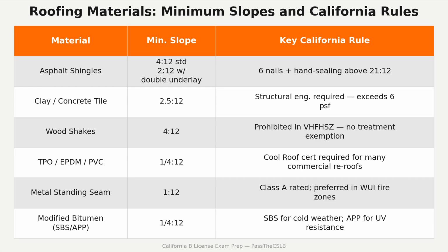Common rafters run the full span from wall plate to ridge. Jack rafters are truncated. They terminate at a hip or valley rafter instead of running the full span. Hip rafters run diagonally from exterior building corners up to the ridge. Valley rafters run from interior corners upward through the concave channels where two roof planes converge.